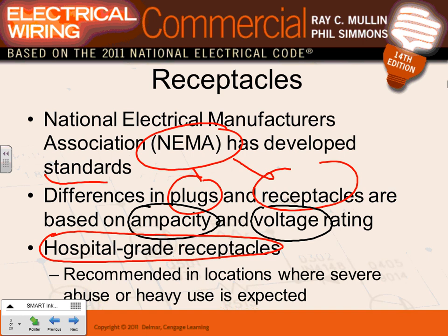With this comes hospital grade receptacle, which is one type of spec type receptacle, where severe abuse is expected. We use them a lot in hospitals too. Heavy use expected. So when it comes to receptacles, can I get you guys to use spec type receptacles, the one that we use, which is more expensive, more robust, can handle more abuse. Everybody's okay with that? Receptacles and switches. Cool. So that's the thing that I want to do.